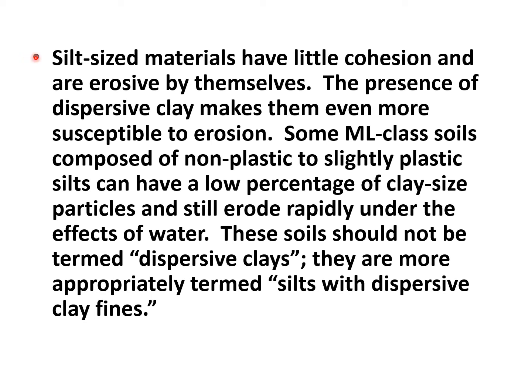Silt-sized materials have little cohesion and are erosive by themselves. The presence of dispersive clay makes them even more susceptible to erosion. Some ML class soils composed of non-plastic to slightly plastic silts can have a low percentage of clay-sized particles and still erode rapidly under the effects of water. These soils should not be termed dispersive clays. They are more appropriately termed silts with dispersive clay fines.